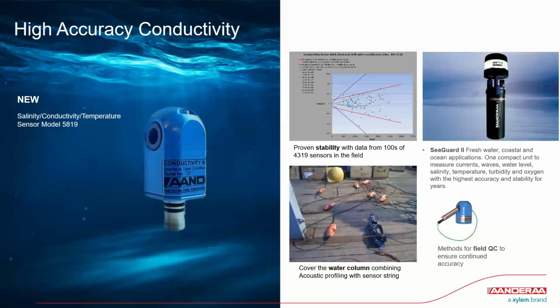Can you say something about what we have for the conductivity? Yeah, I think for the conductivity it is particularly easy with these resistor loops that we're using. I think it's always nice in the field to be able to do that last check to see that your sensor is working correctly, that everything is okay before you deploy, maybe for a long period of time. So these easy quality assurances that you can do with an inductive sensor, where you connect a resistor loop, are very nice for simple checks. So this easy field quality assurance is definitely the way to go.